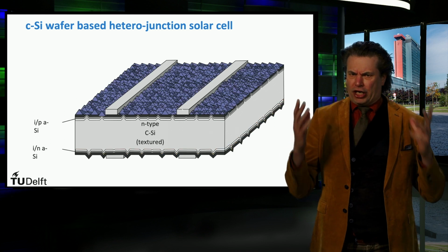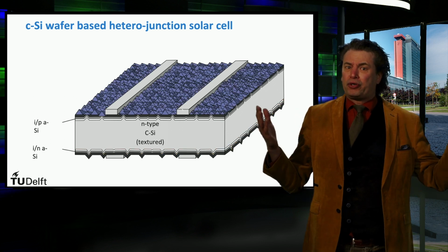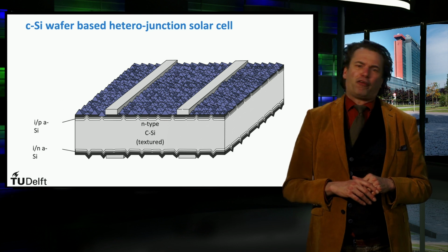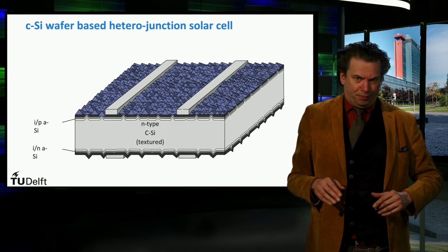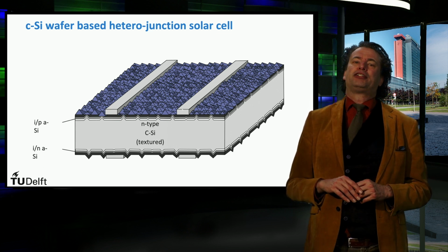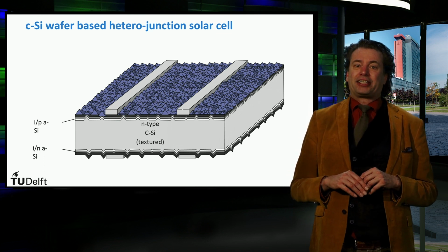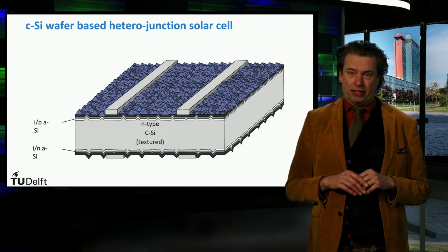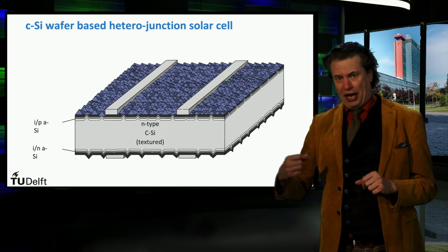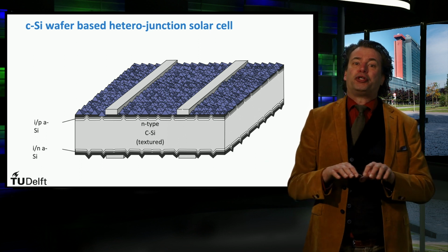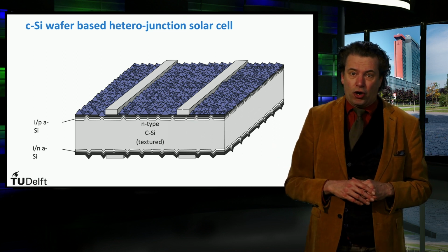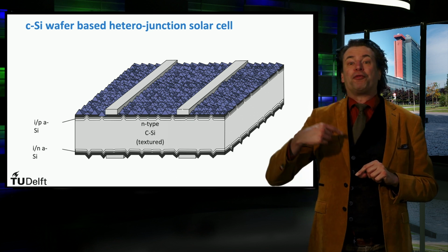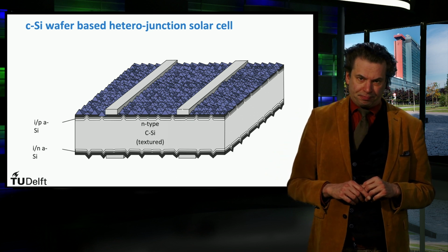How do the charge carriers travel to the contact? The conductive properties of the p-doped amorphous silicon are relatively poor. In the homojunction solar cells, the diffusion to the contacts takes place in the emitter layer. In contrast, in a heterojunction solar cell, this occurs through the transparent conductive oxide material like an ITO, which is deposited on top of the p-doped layer.